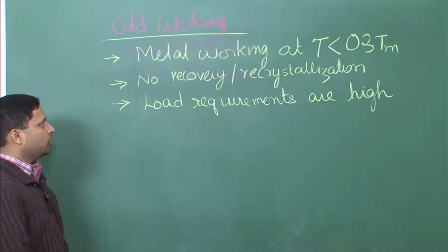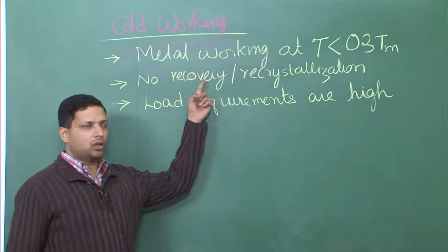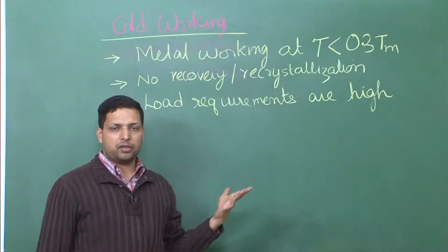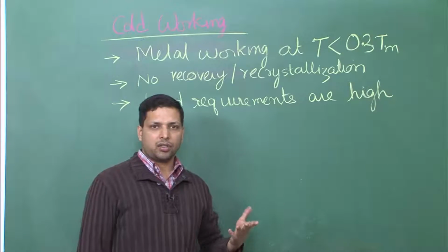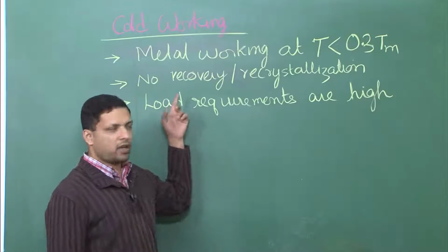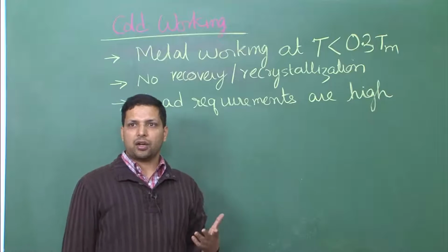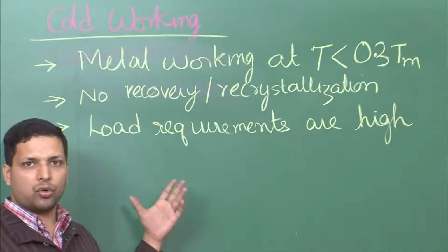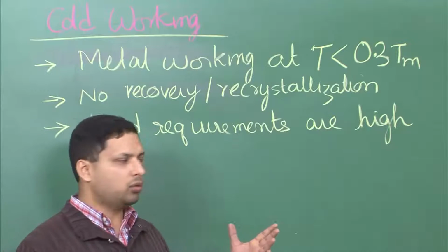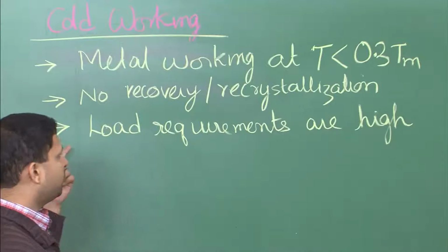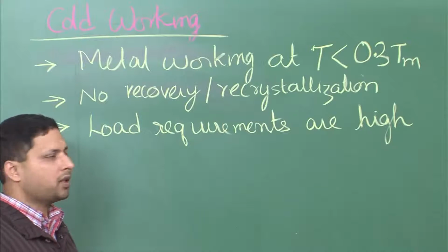And it is related to the fact that no recovery or recrystallization is taking place. Remember, recrystallization is what? In simple terms, it is the creation of new strain free grains. If no new strain free grains are getting formed, these are old strained work hardened grains, and therefore, you need more and more or higher and higher stress to deform to a higher level, to a higher strain value, and therefore, load requirements for cold work is high.